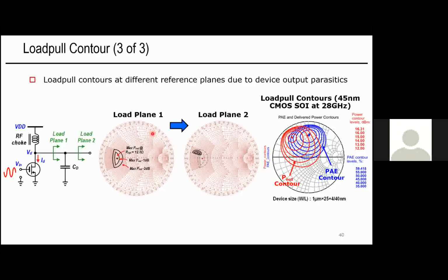Can you repeat? My question is about the load pull characterization of the devices from a device design point of view. When we are doing only single tone measurements, is that going to affect our gamma L? For example, if the input power is only a single tone. And one more question is about the level of the P-in when we are considering our best or optimum gamma L. At different P-ins, for example at P-in -1 dB or 6 dB back off, our gamma L is going to be different. So what will be the best way to consider the optimum gamma L?